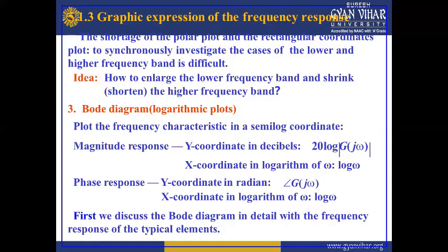The y coordinates are in decibels, given as 20 log magnitude of G(j omega), and the x coordinates are in the logarithm of omega. The phase response is plotted against the logarithm of omega. First we will discuss the Bode diagram in detail with the frequency response of the typical elements.